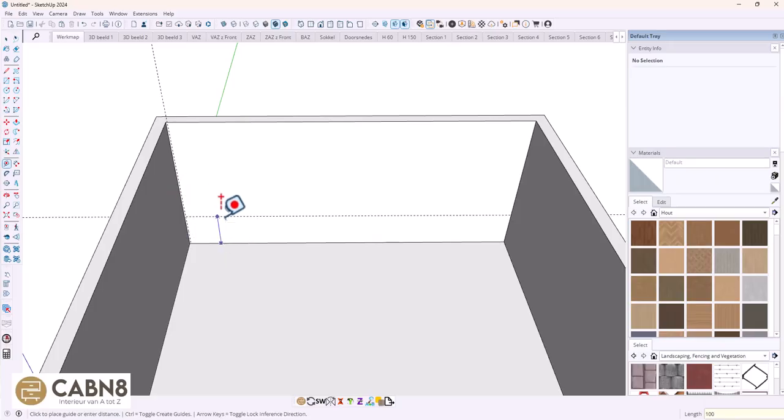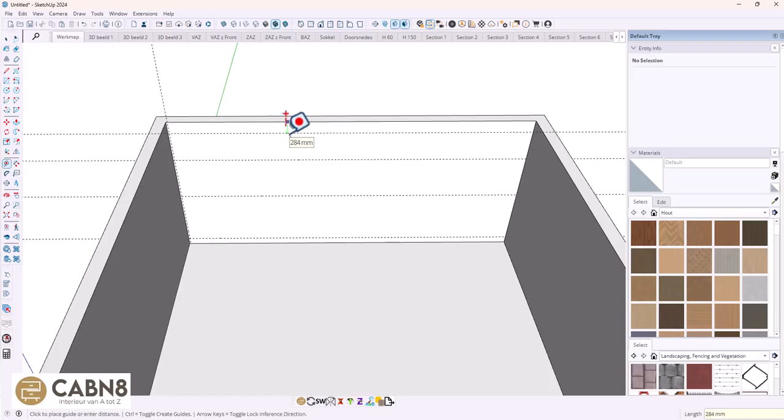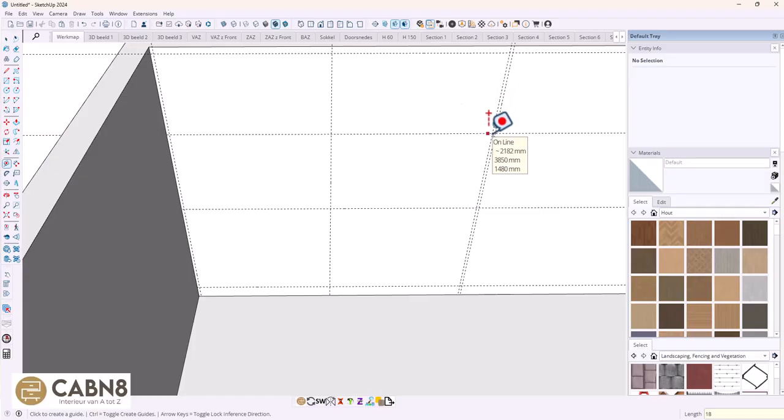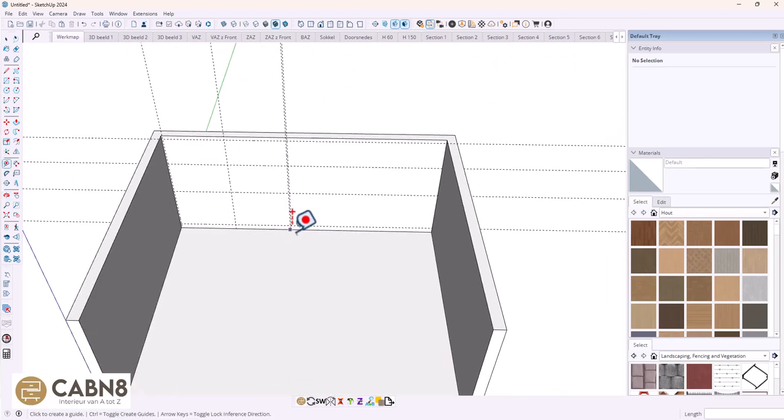From the bottom, 100 for the skirting board, 78 for the cabinet, 600 between the cabinets, and then from the top also 100. On both then the wall cabinets, their measurements are 102 centimeters, and another 102, one panel of 18, and the rest I won't be needing. Then for the depth, we'll set this here to 700.